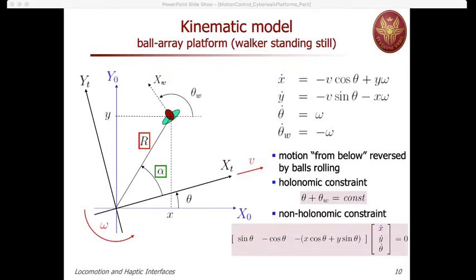This type of consideration, for those of you who have taken the course of autonomous and mobile robotics, and in particular have derived kinematic models for mobile robots, is something that you should know already. But in that context, the reasoning is reversed. You start by imposing some non-holonomic constraint, for instance, due to the fact that the wheels are in pure rolling on the ground, and from there you derive a model which specifies what are the feasible motions for the system. Here this non-holonomic constraint was found a posteriori, but still the situation is pretty much the same, so that whatever control method that you have developed or you may think of for a wheeled mobile robot could be applied as well to this situation.